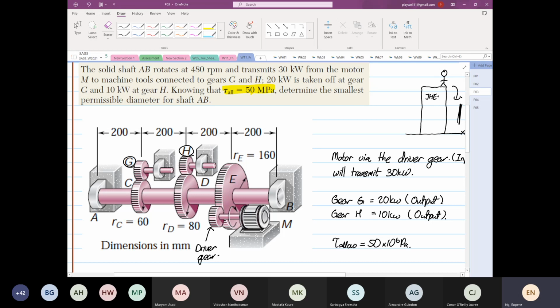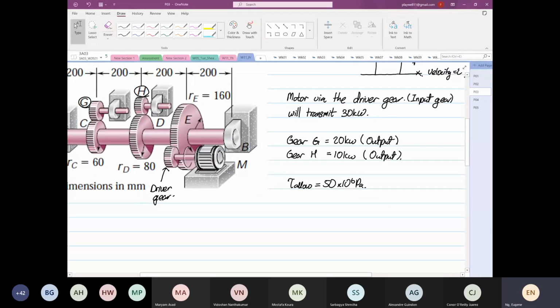Okay, because by integrating Mohr's circle together with structure analysis of the shaft under torsion, under bending, we are going to use Mohr's circle, and the criteria is going to be allowable shear, because the shear stress has a lower magnitude than the normal stress in yield. Period. Done.